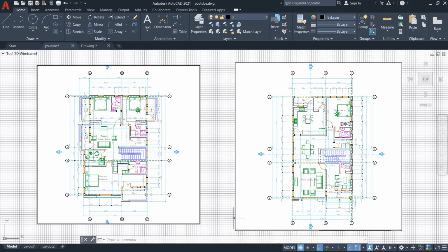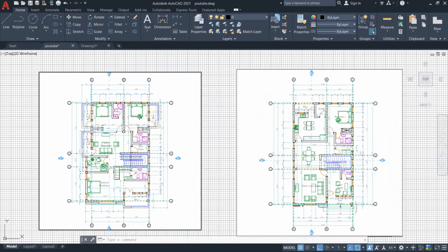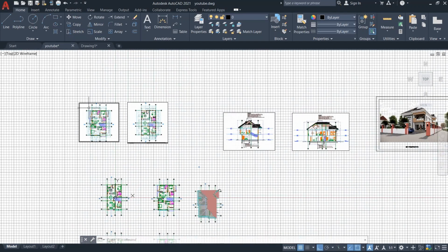Also, we have to look out for the cantilevers here. You can see that this is the ground floor, and this is the first floor. If we look closely, we can see that this here is going to be a cantilever. The cantilever could be a cantilever slab. Since you can see here, there's surely going to be a slab, then the roof beams surely cantilever out. So if you understand that, we're good to go.